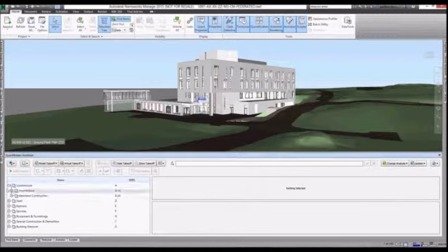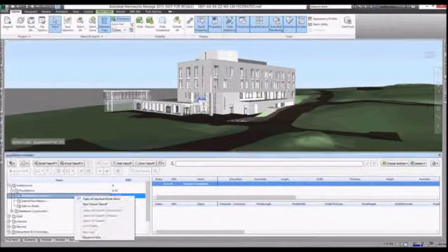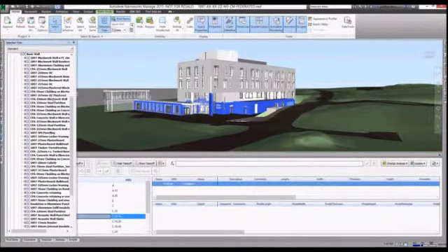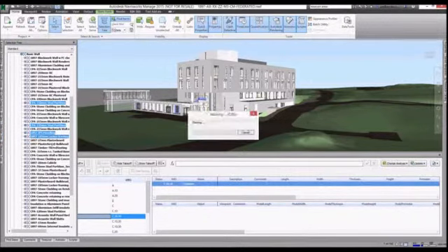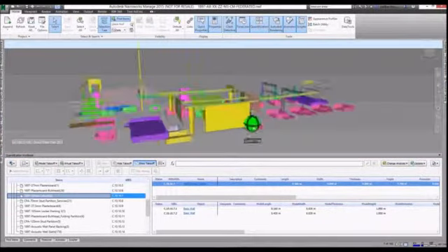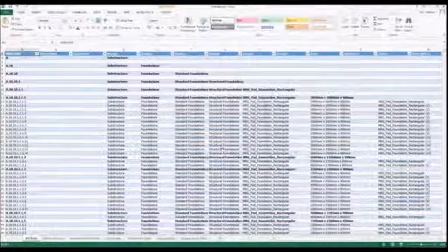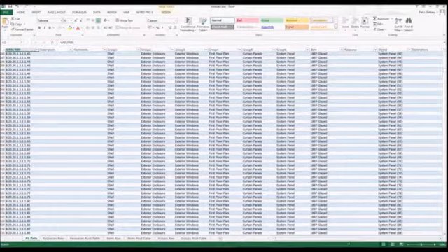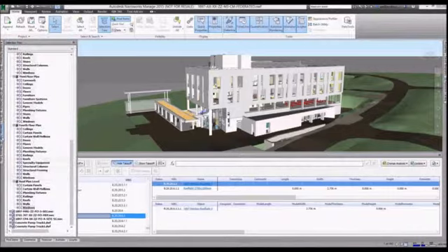Navisworks also includes quantification tools that allow you to create catalog recipes for taking off elements in the model, either 3D Model Takeoff or 2D Takeoff from drawing sheets. 3D Takeoff allows elements to be highlighted in the model and attached to items in the workbook. Items which have been taken off can be isolated or hidden in any view. You continue to highlight and take off the model elements, and should the model be updated at any stage, the Change Analysis tool will identify and highlight the differences. The takeoff can be exported to Excel if required, and possibly linked to other quantification and bill creating tools.